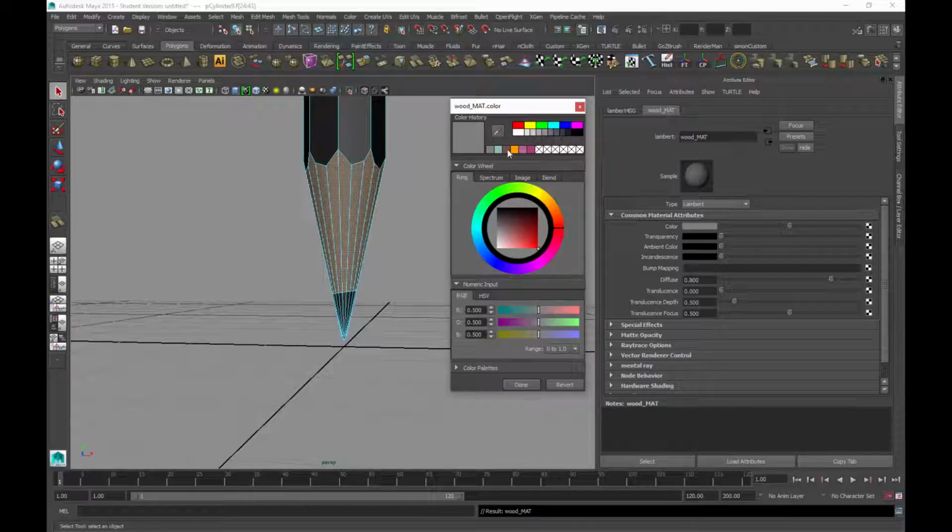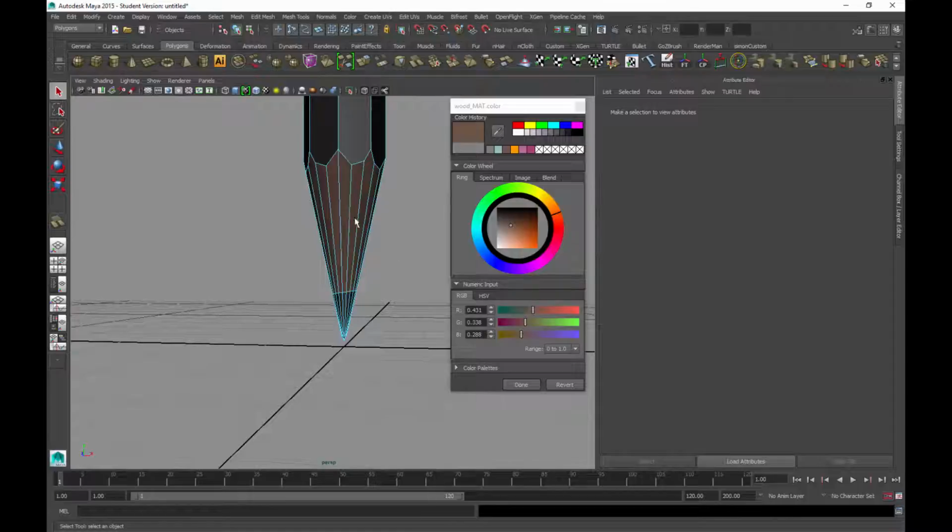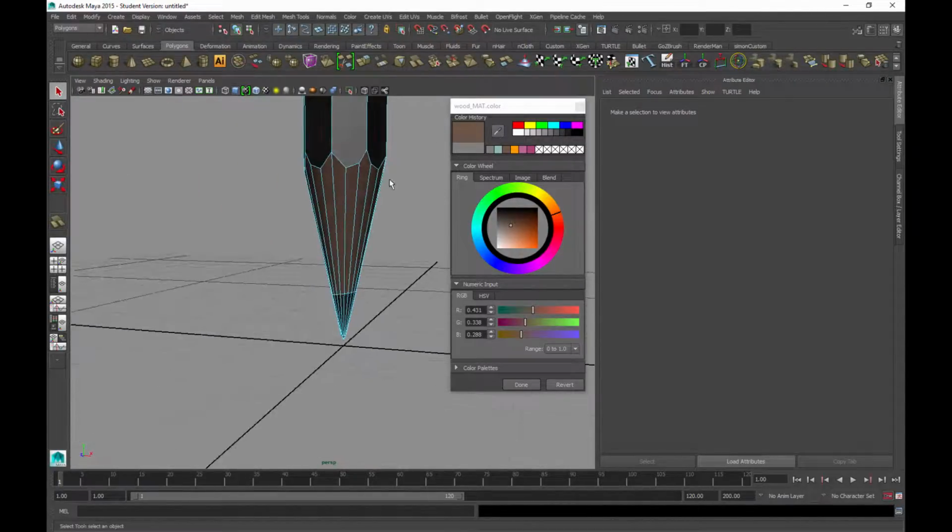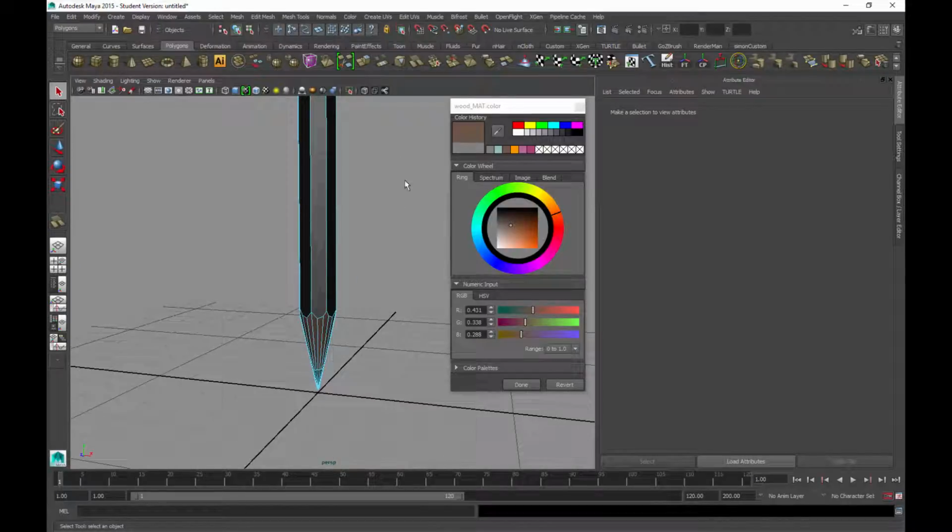So what I want to do is create a color that's roughly here, this brown color. You'll need to move this dot about here, and then dial this around until it's in this orangey red area, and that'll give you a brown color. You can see the RGB numbers there, so you could type those in as well. You can switch your color picker to HSV or RGB as well. Okay, so I want a brown color, so just select that from the color picker. If I deselect over here by clicking in an empty spot in the grid, you can see that brown color is on there now, like that. Okay, so just click in an empty spot on the grid.